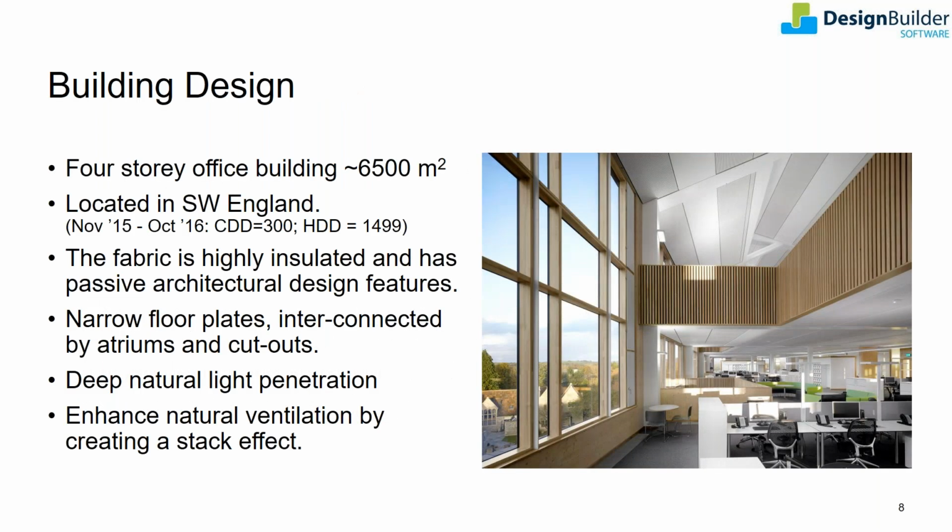The 4-story office building is located in southwest England. It is highly insulated fabric. The building has many passive design features. It has high ceilings and narrow floor plates which are interconnected with atriums and cutouts. This leads to the building having deep natural light penetration and stack effect based natural ventilation.